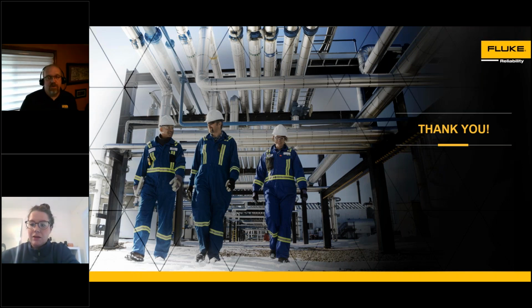You need to make sure that you do a survey of the machine, depending on whether you're talking about a complex machine or a simple machine. And I say a simple machine, it's fairly straightforward. So a simple machine being like a pump motor combination or a motor fan combination. So you want to make sure that you know what your horsepower is, what bearings you have in there, things like that, and make sure that you keep that accurate and updated in your database.